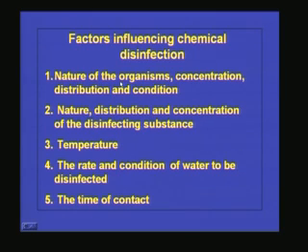the system. The nature of microorganism means if it is in colloidal form, or present as discrete particles in the water, then it is very easy to destroy them. The reason is the chemical will go and attack them directly. But if the microorganisms are in the form of flocs, what will happen? The microorganisms on the outer surface of the floc will be exposed to the chemical, but whatever is sitting inside will not be exposed that much. Unless the chemical dose is very high, the microorganisms in the center of the floc will not be destroyed.